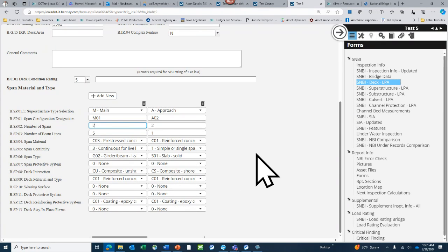Most bridges you have are going to have a main span or a main structure type, and that's it. It's all pre-stressed girders. It's all a slab. It's all steel girders. The whole bridge is the same, so you'll only have one input here. You only have additional inputs if you have a different structure type altogether. That's why I say even widening, you don't have a widening if the structure type is the same.